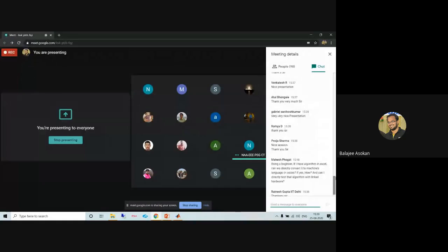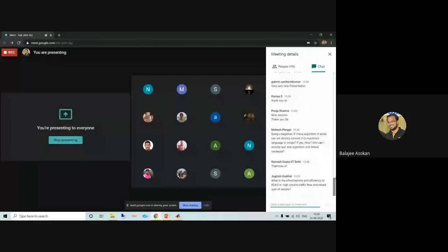So one thing is, for a beginner, you cannot convert your algorithm directly into machine language code. Your machine language code is not a mere C file. Your machine language is something in the form of zeros and ones, along with the object file and .a file. There are certain tools and packages, and most of these tools and packages are OEM specific. Bosch has their own set of tools to convert C code into machine language code.